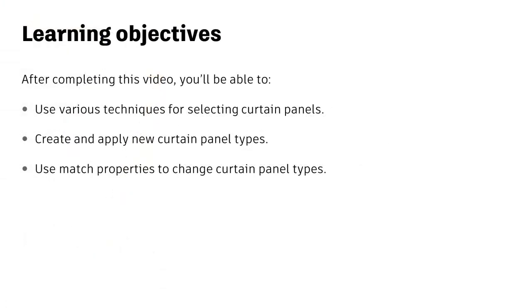In this video, we'll see how to use different techniques for selecting curtain panels within a curtain wall. We'll see how to create and apply new curtain panel types, and we'll also see how to use the Match Type Properties tool to assign curtain panel types into a curtain wall.